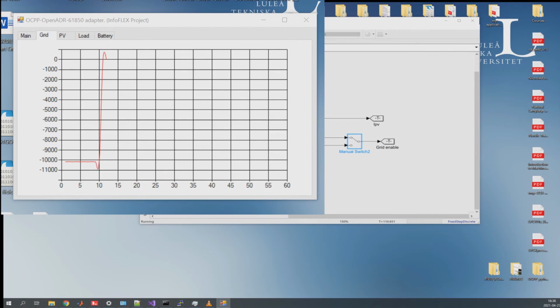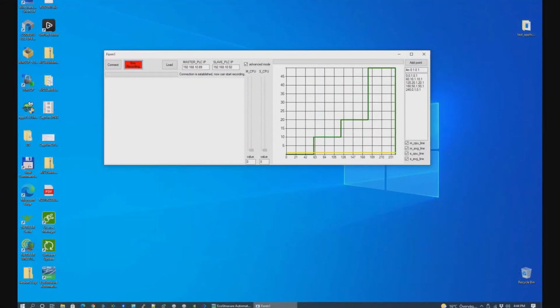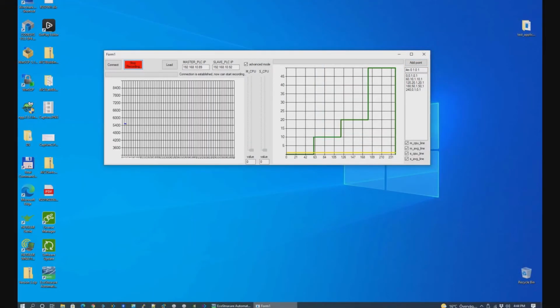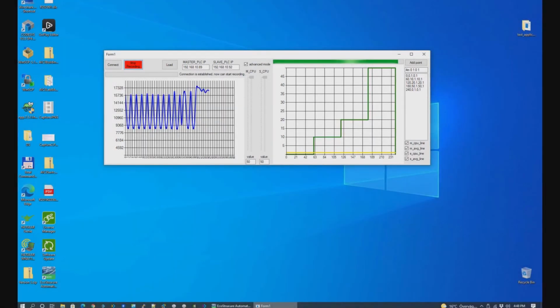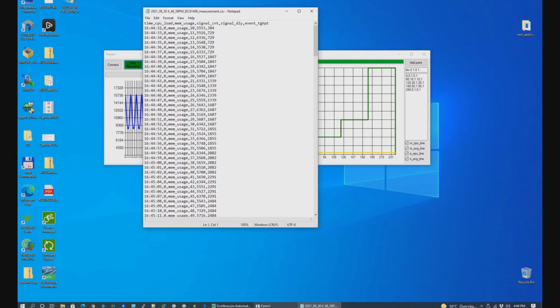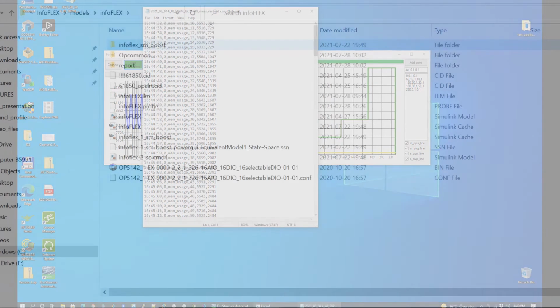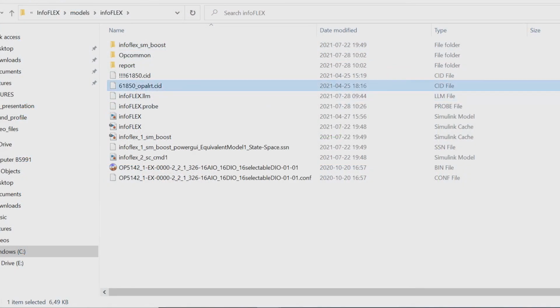The theoretical amount of energy produced and consumed under various conditions. During a short-term simulation, investigate the behavior of the PLC as a control tool. Check for errors in the control algorithm, or possible shortcomings. During a long-term simulation, it is possible to investigate the resistance to failure of the developed algorithm. For example, I can collect information about the signal latency of the PLC, and then analyze this data. I can find the minimum and maximum values of signal latency, the mean and the 75th quantile.